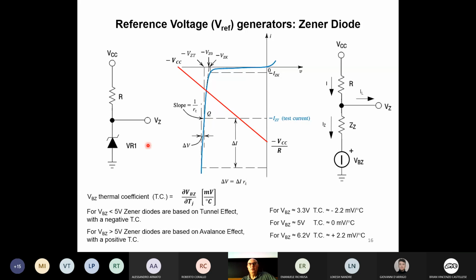Do you remember that Zener diodes were particular diodes which were operated in reverse bias, and they used some breakdown phenomenon? That's the typical characteristic of a Zener diode. The Zener diode can actually also be used in a direct way. If we have a direct biasing of the diode, we are working here in the first quadrant. We put a positive voltage, and we have a positive current. Here it is a bit expanded, but we could say that there is a 0.6 volt knee, and after the 0.6 volt knee, the current starts to increase. The picture is very zoomed, so this shape here is actually an exponential, if you remember.